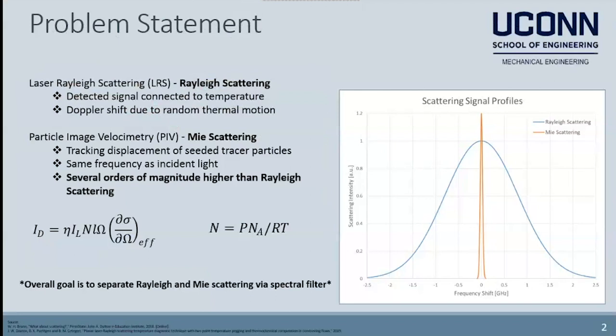Measurements to analyze the detailed structure of a flame are quite complex. In order to achieve a better understanding, several laser diagnostics have been developed to determine flow field properties such as temperature and velocity. A laser sheet is directed through the flow, and a scattering signal is detected with an intensified camera. Light scattering is when light is absorbed by particles and then subsequently re-emitted at a different wavelength.